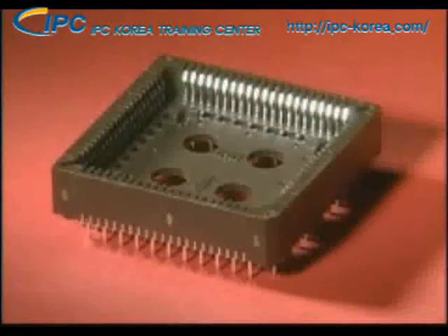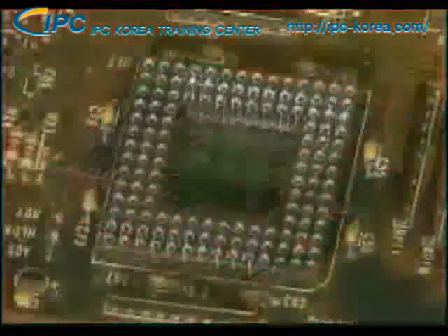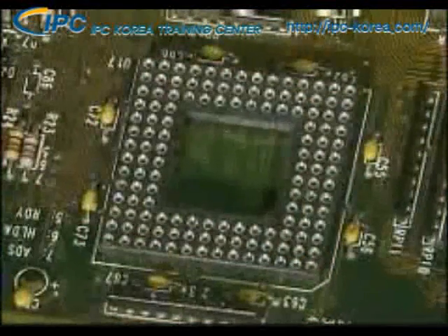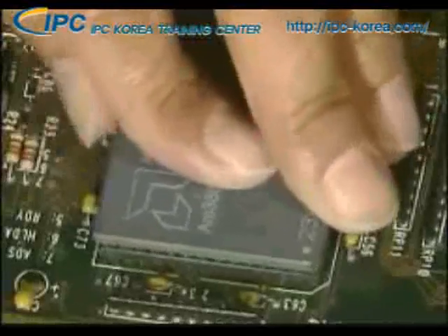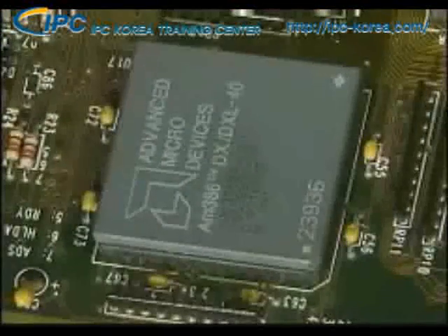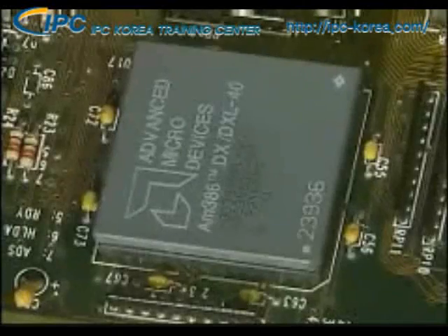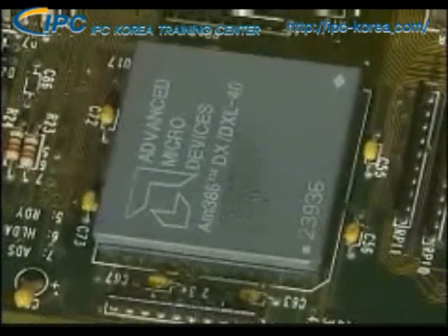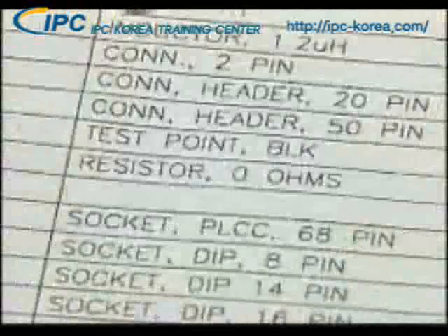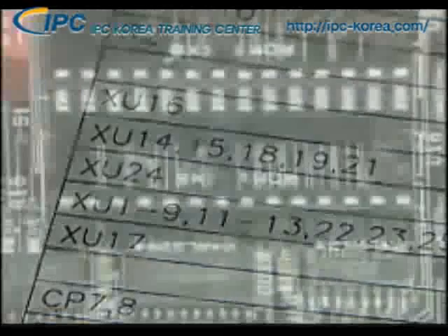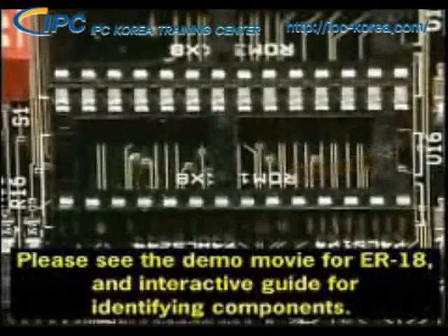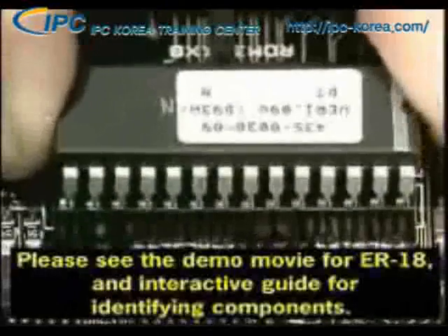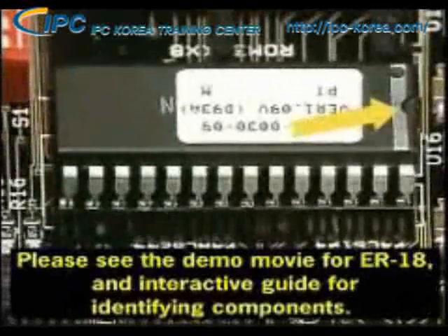Another type of connecting hardware is a socket. Sockets are soldered onto a circuit board so that an IC or PGA can be plugged into the socket without being soldered. This makes it easier to remove and replace a component that might be upgraded or changed in the future. The reference designator for a socket is some variation of the letter X. Sockets usually have a notch or dot to indicate orientation. The component being plugged into the socket will have an identical orientation mark.